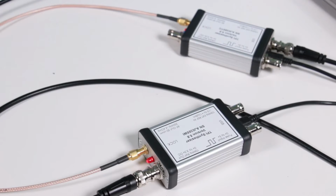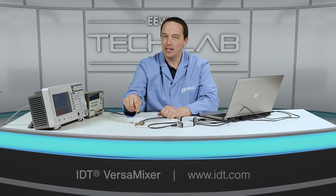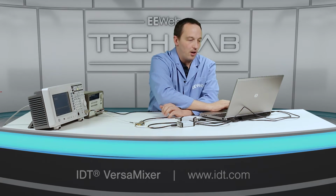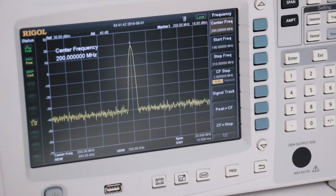Now these are uncalibrated, but they're both set to about plus 6 dBm. It's as low as they'll go. And the gain settings on the eval board haven't been changed, so that should be sitting at about 11 dB. So we should see a signal somewhere around 17 dBm here. So if I turn my RF outputs on, we have our 200 megahertz signal and it's sitting just under 17 dBm.